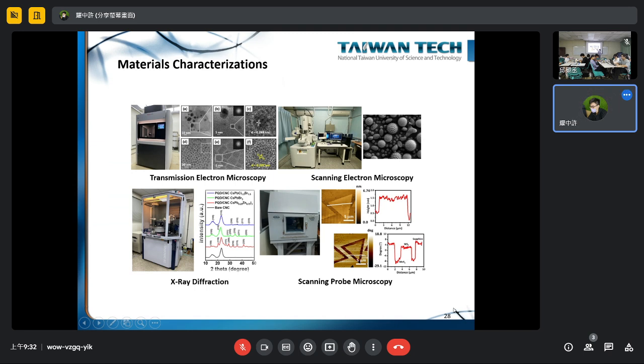So we don't usually only use the two lines that we see here. This is called direct observation. Instead, the more accurate way is you go from the diffraction pattern back to your plane distance. So that's how TEM works. And also scanning electron microscopy, I think most of you may have known that by detecting the electrons emitted from your sample, you can get the surface morphology of your material.